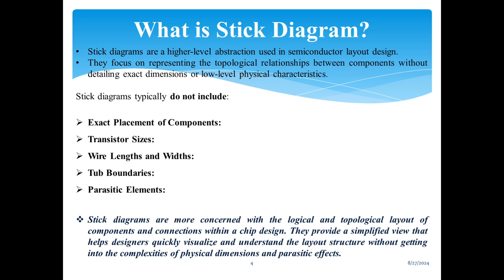Transistor sizes. They do not indicate the dimensions like width or length of the transistors or other components. Wire lengths and widths. Stick diagrams do not specify the exact lengths and widths of wires used for connections. Tub boundaries. They do not depict the exact boundaries of transistor regions, such as diffusion or wells. Parasitic elements. Stick diagrams do not include parasitic elements like capacitances and resistances that naturally occur due to the physical